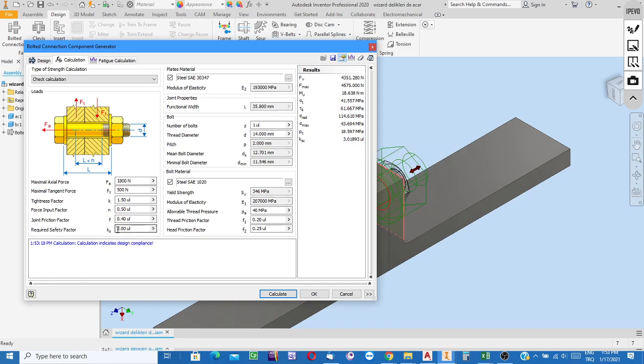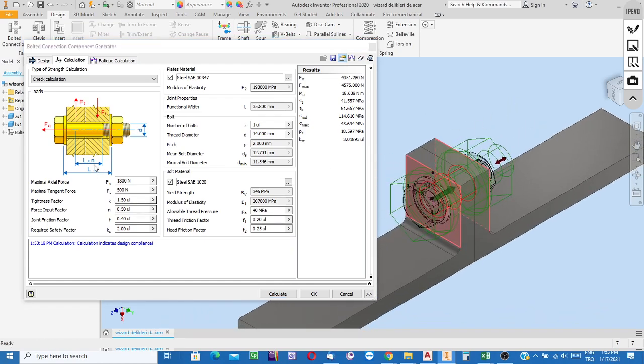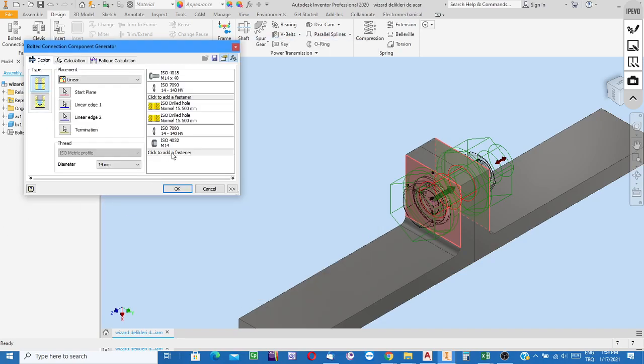Although I said that a factor of safety of 2, two times on the safe side, is sufficient. Now, of course, to be able to save material, after seeing that the 14 millimeter bolt size enables us to be 3 times on the safety side, we can decrease the diameter, not 10, not 14, but try to use the standard bolt, 12 millimeters.